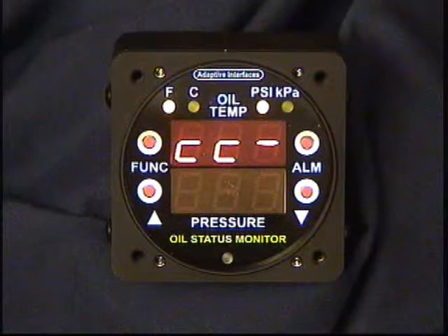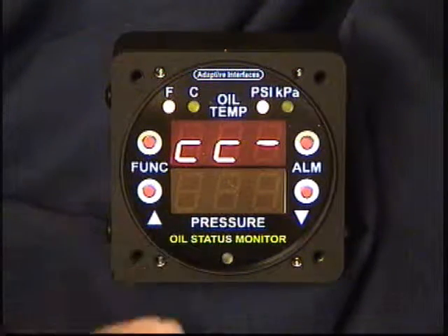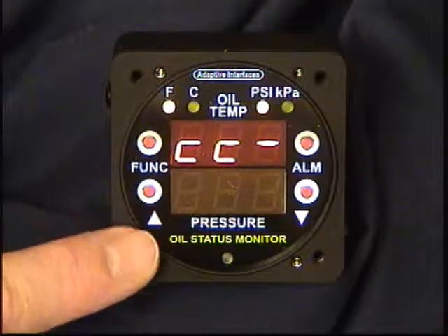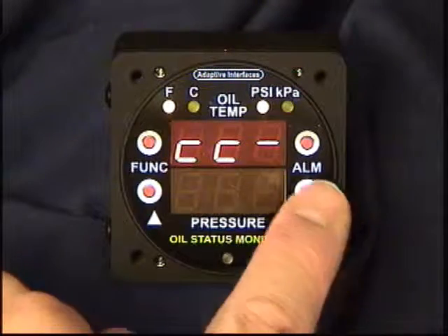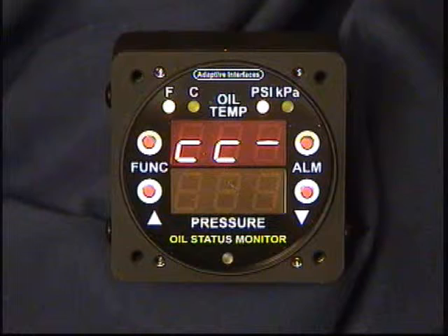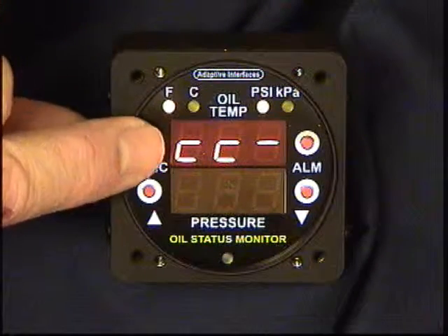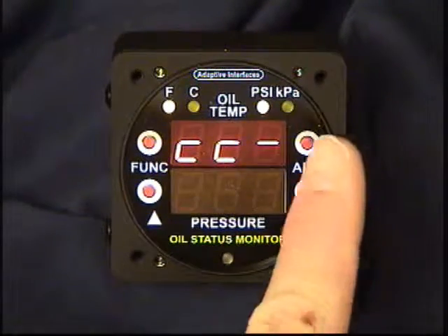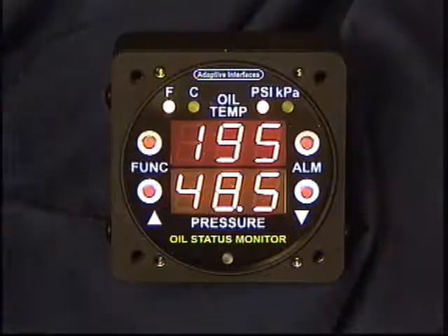If we go to a double return, it would always go back to the main operating mode or menu level 0. Again, to select a setting or a function, the alarm button is used as an enter button. And in any menu level other than menu level 0, the alarm button is considered an enter button for doing various settings. We will now use this button. We'll go back to menu level 0.